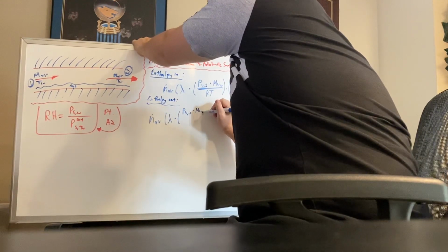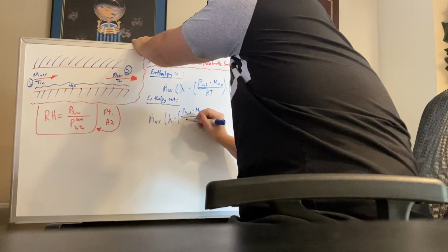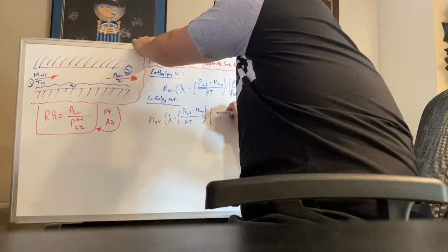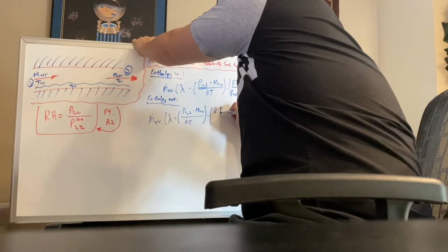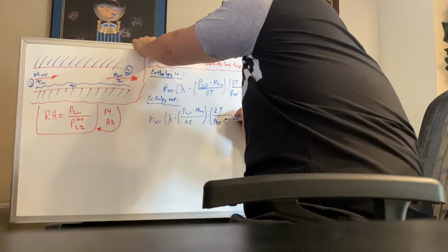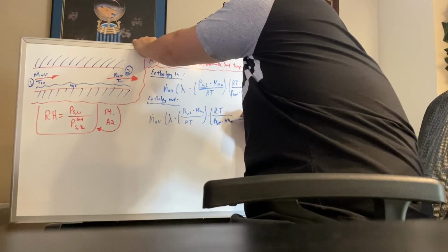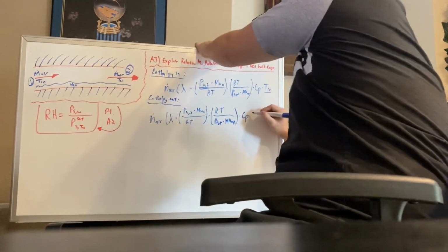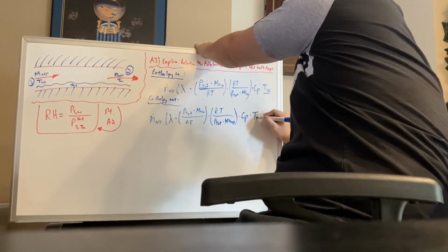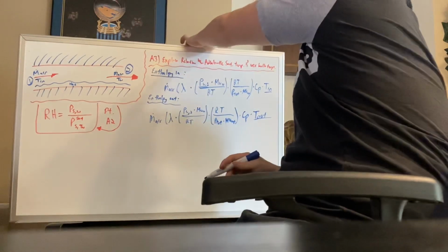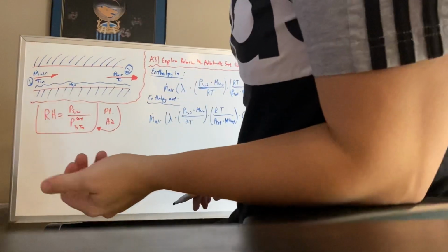This will be multiplied by the molecular weight of water again, all over the gas constant times the temperature, multiplied by the gas constant times the temperature again, all over the total pressure multiplied by the average molecular weight. This will also be multiplied by the specific heat capacity and the temperature of the outlet feed. So once again, these are the two main differences between the two, and how we will be looking at that for future reference.